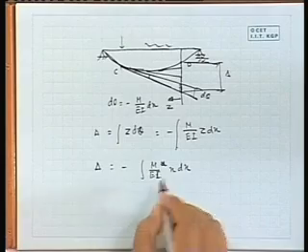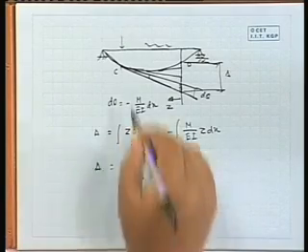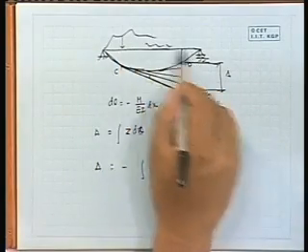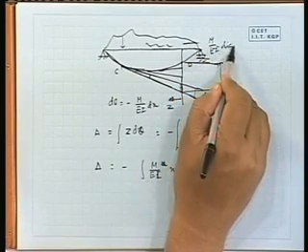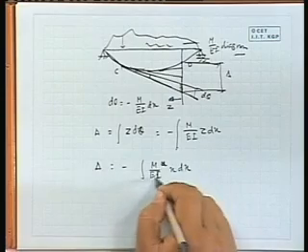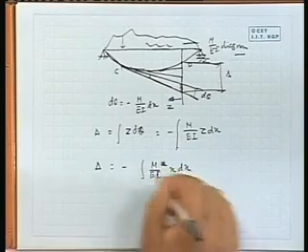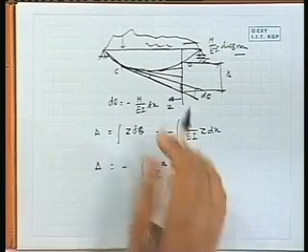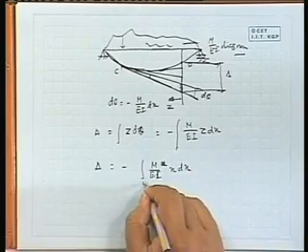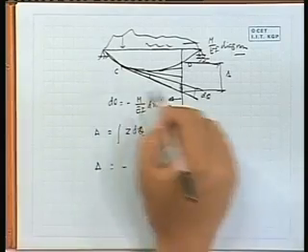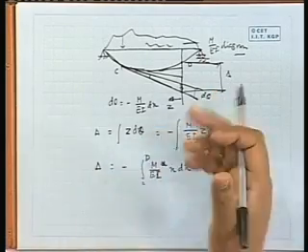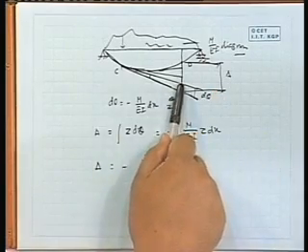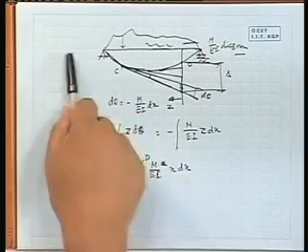So here what we are getting, delta equal to M by EI diagram, that is x into dx. So we say this is the first moment of area of this diagram between your C to D, but this x or z whatever we are talking about, you have to take from here, okay, not from here.